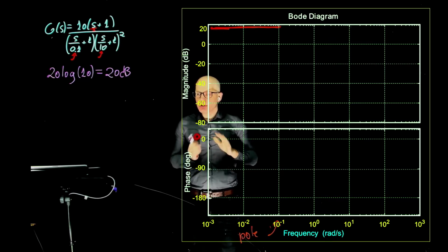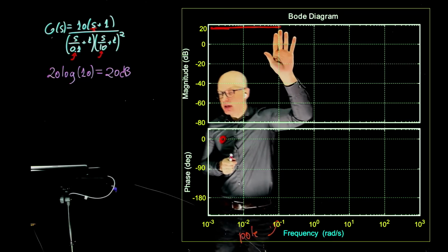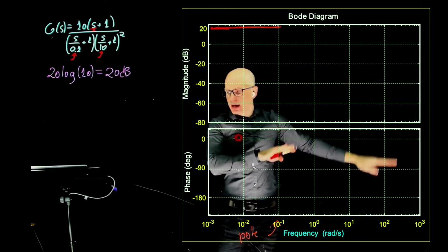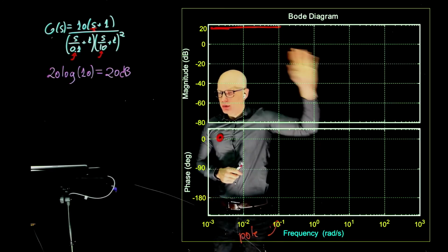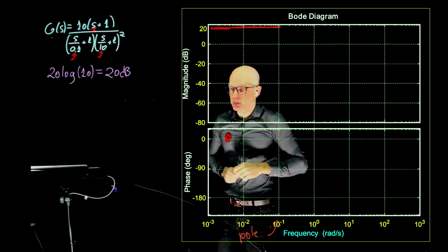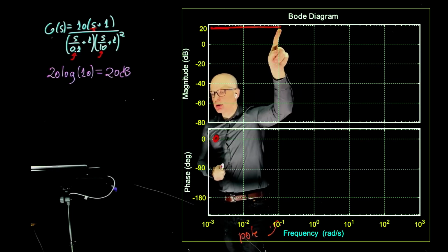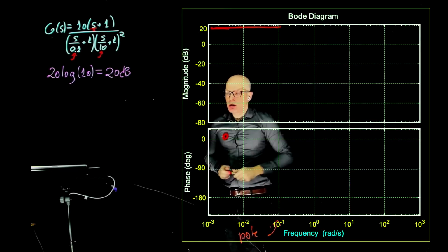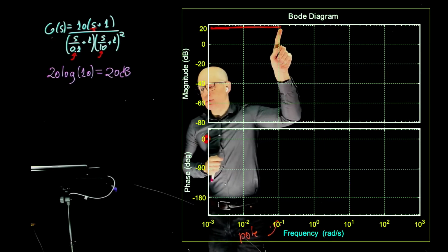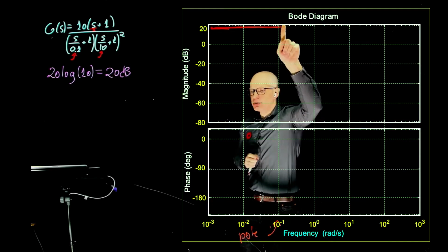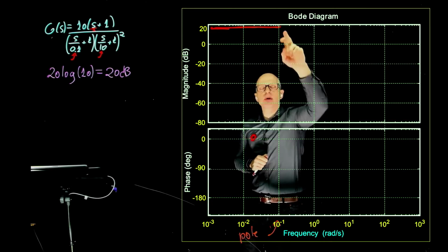Okay. So for simplicity, let's forget about the -3 here because it shifts everything down later, but we can account for that later on. For now, let's just focus on the slope. But you're right, at this point, because it is a cutoff frequency, the magnitude would drop by 3 decibels and it would be 17 dB. All right, but let's assume that it stays, let's forget about that -3 and just focus on the slope.